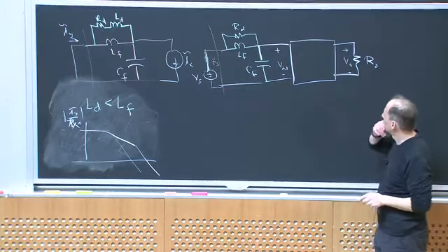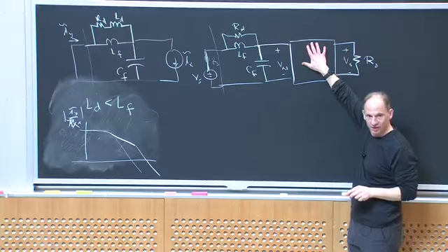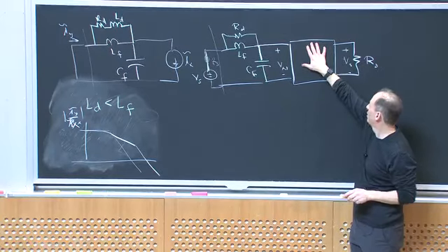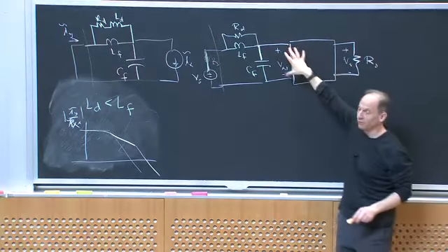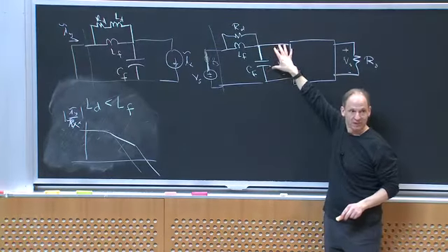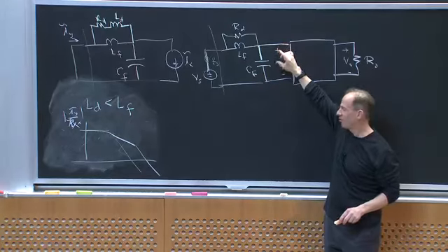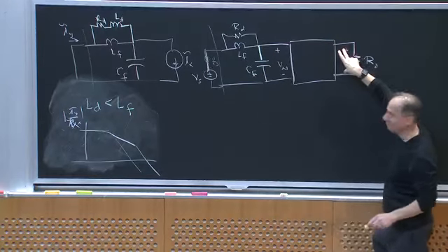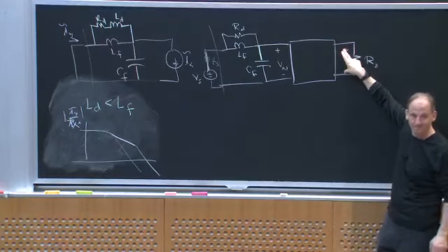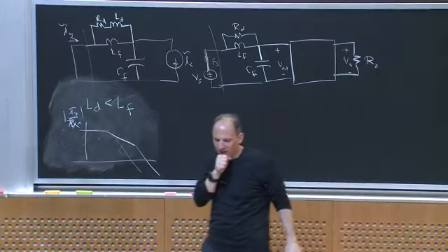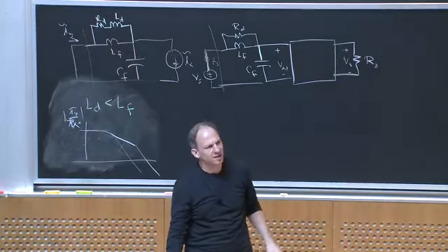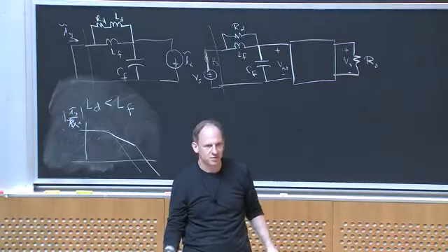All right. What does this power converter do? Let's assume he's a perfect power converter. He's going to keep the output voltage at the reference no matter what the input voltage does. Right? That's his job. Input voltage varies, I don't care. I'm going to keep 12 volts at the output no matter what. Okay? So what would I say that he does? Well, he's a constant power load in that case, right?